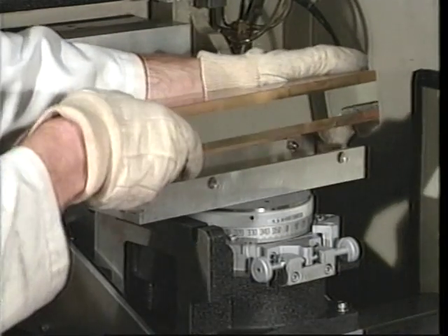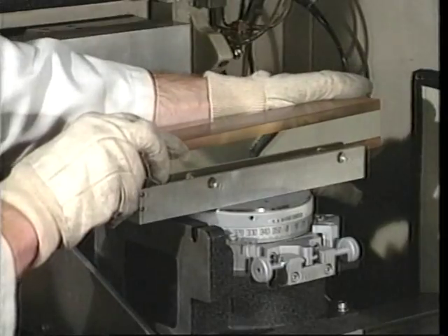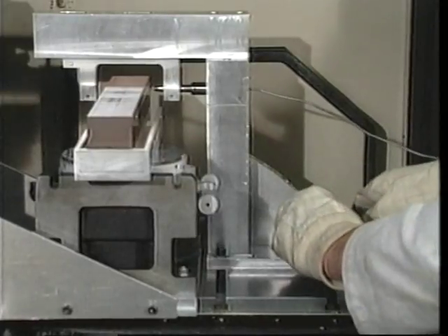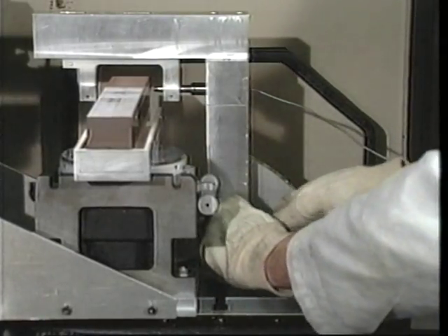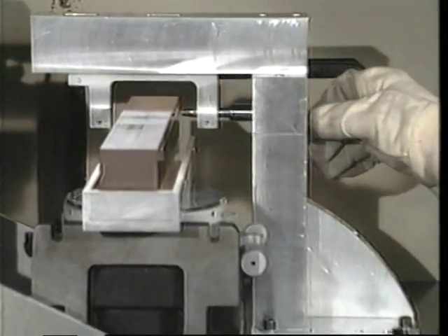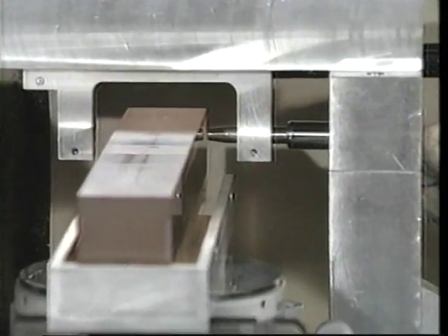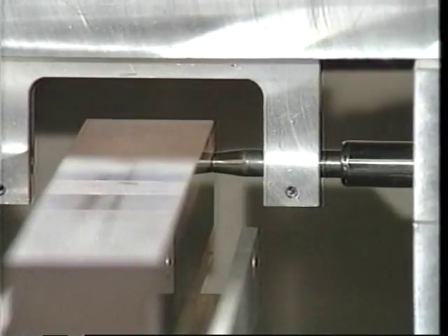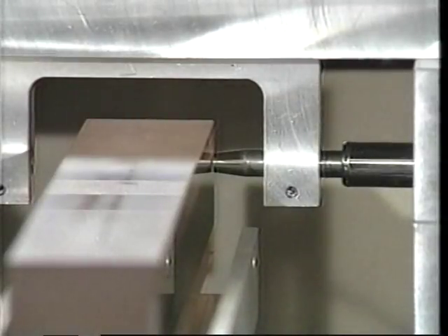The optical straight edge is carefully placed in the cradle. The capacitance gauge is mounted to the x-axis slide such that it probes the reference surface of the straight edge. The capacitance gauge will measure the lateral motion error of the moving slide and the irregularities in the reference surface. As you recall, the non-contacting probe will sense changes in the separation of the probe tip and the reference surface by measuring the changes in the capacitance of the target area on the reference surface and the sensing area of the probe.